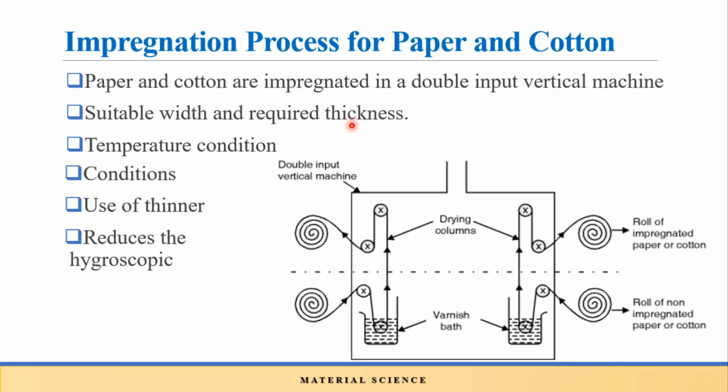Due to this, the electric field also becomes non-uniform in that material. Whenever you are using such fibrous insulating material, if there is an electric field, it will get non-uniformly distributed over the surface of that insulating material, which leads to breakdown.